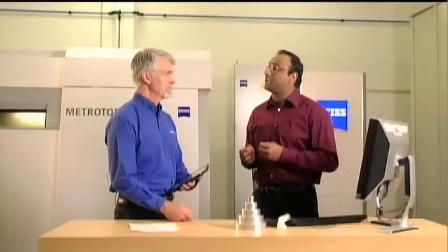So with ZEISS, we have the ability to use the same guideways, the same scales, and the rotary tables that are used on our high precision CMMs to avoid most of those problems that normally happen during CT scanning. Okay. The second stage is the data reconstruction stage. That is where you basically define where the true edge for your part is. I have a little artifact to illustrate what edge definition is and what we do to get accurate data sets.